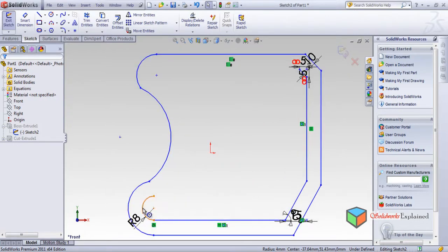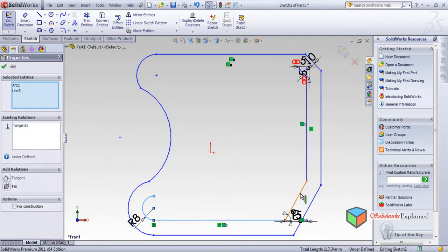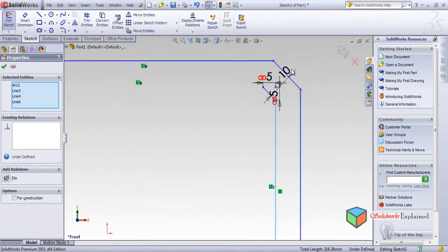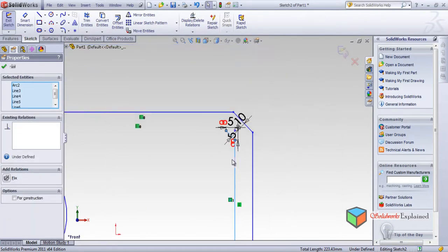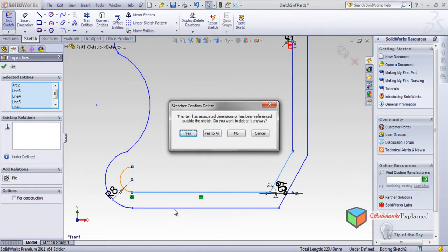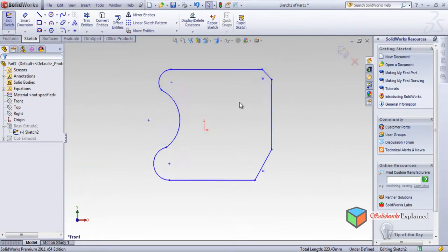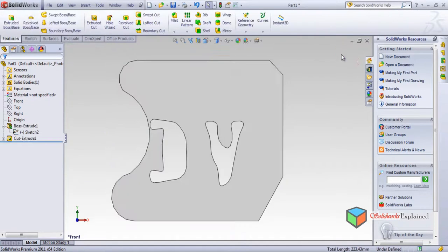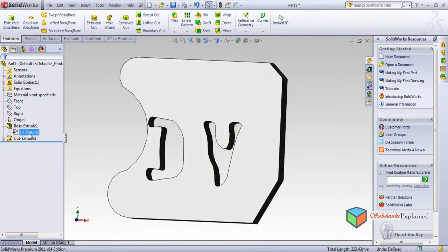In this case I can also click here, control, click here, control, also zoom in here, control, click. Everything is selected now, delete with the help of the keyboard. Okay, now this is done, and we'll make it back. So look, now you offsetted everything.